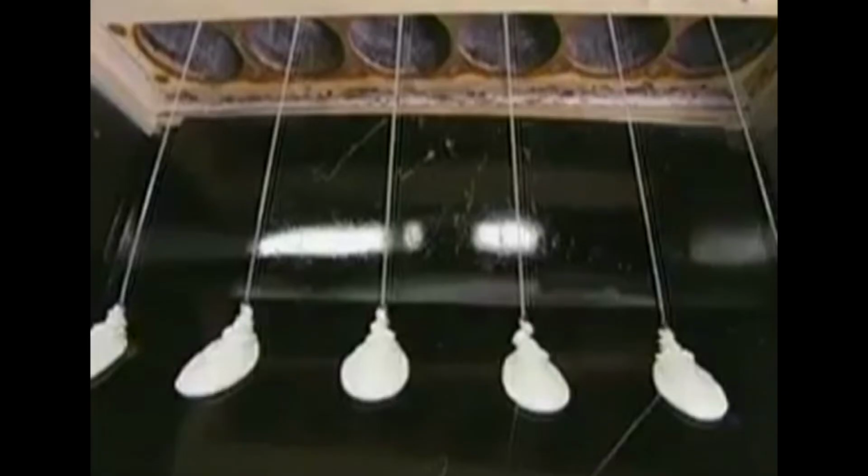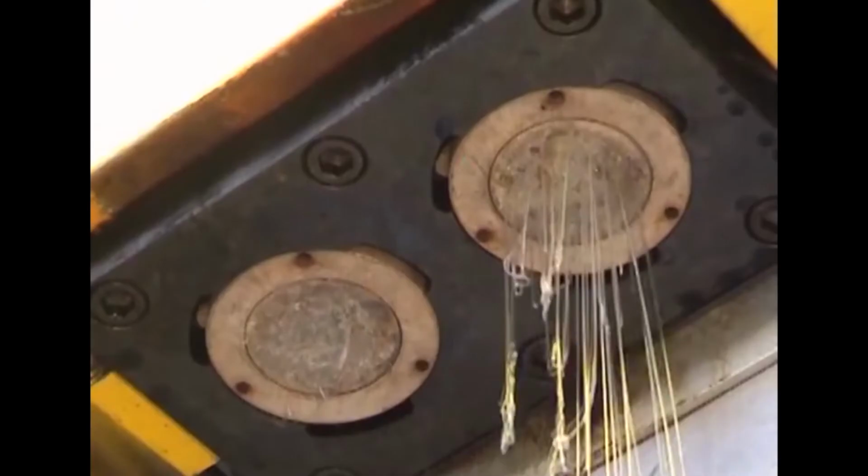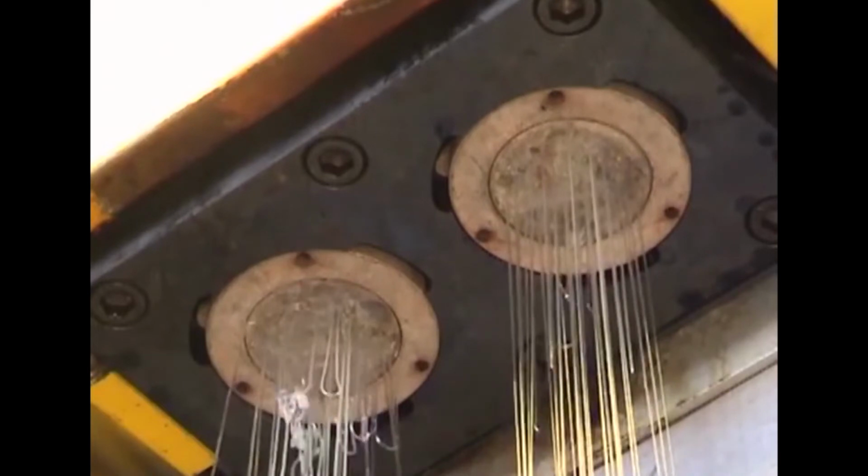And so, it will first be filtered to remove all the suspended particles and then vacuum treated. If it contains a small air bubble, that also will interfere with the formation of longer and continuous filaments. And so, this is vacuum treated to remove the air bubbles, and then it is stored in the storage tanks. From the storage tank, the molten solution, that is a free flowing polymer, is made to pass through the holes of the spinneret.